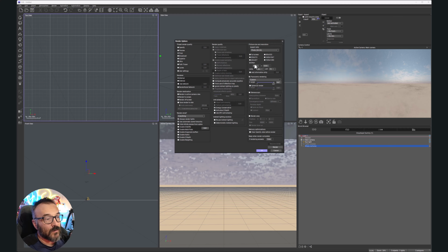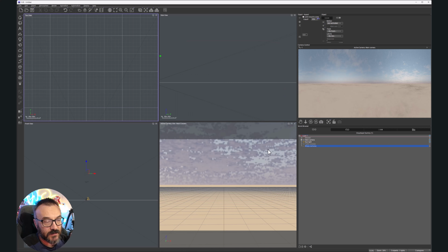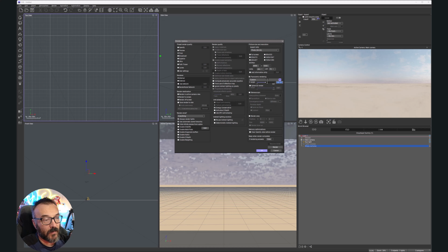We have it, click on the render, and notice because we selected panoramic, when we close and open, it comes up with options that ask what angle, and you can modify here. Remember what you want: spherical, VR 360, cube, all these different versions. In general, we have 360 on the horizontal, and you can have it just maybe 180, like this, set on horizontal. Let's click OK, and then you can manage and manipulate what angles you want to render on the horizontal. Sorry, it's 180 flat up front of us, or we can go and modify.